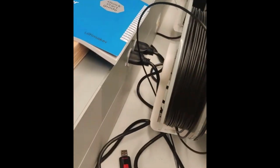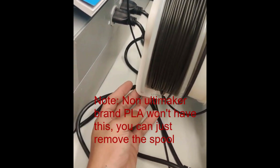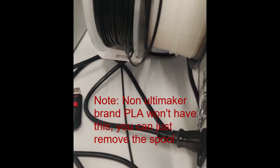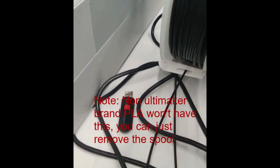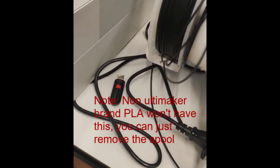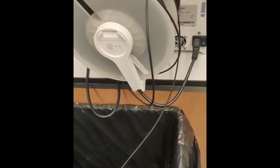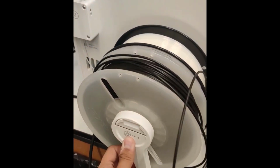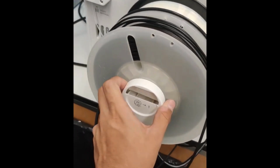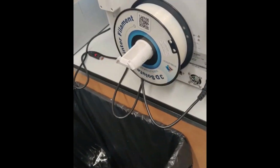And so now what we're going to do is actually take the spool out. There's this little accessory that comes with the Ultimaker. The first thing we're going to want to do is unthread it this way. So we'll pull on it until we have no amount of spool coming from this little area right here. I turned the Ultimaker to make it a little easier to see, but once you have that done, you can now remove this little accessory and the spool at the same time, just like that.